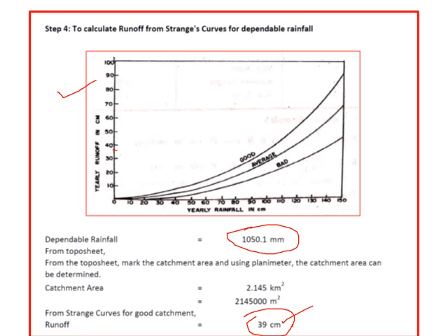The next step is to know the catchment area. It is not the capacity contours that you have generated, and the area enclosed between the curves is not the catchment area. The catchment area is totally different. What you have to do is take a topo sheet, mark the ridge lines, and then get the catchment area from the planimeter.